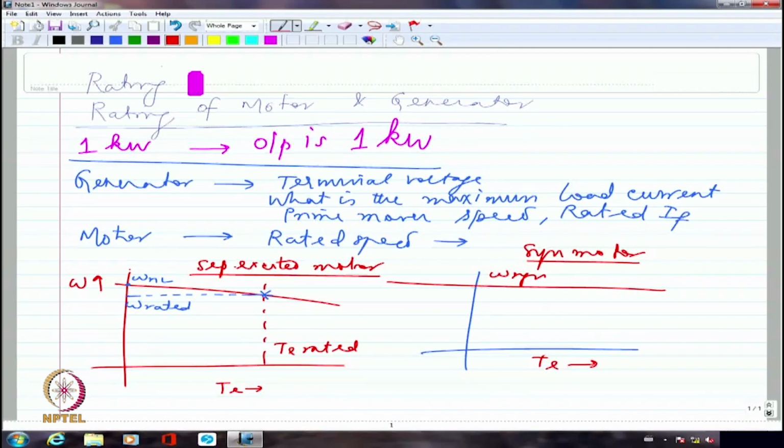And we are going to say that this is the maximum kilowatt that it can supply. So if I say VT multiplied by IL is the total power drawn by the motor, this will be greater than the kilowatt output, clearly, because the efficiency cannot be 100%. And the kilowatt output, what is measured, is mechanical in nature. So it is torque multiplied by speed.